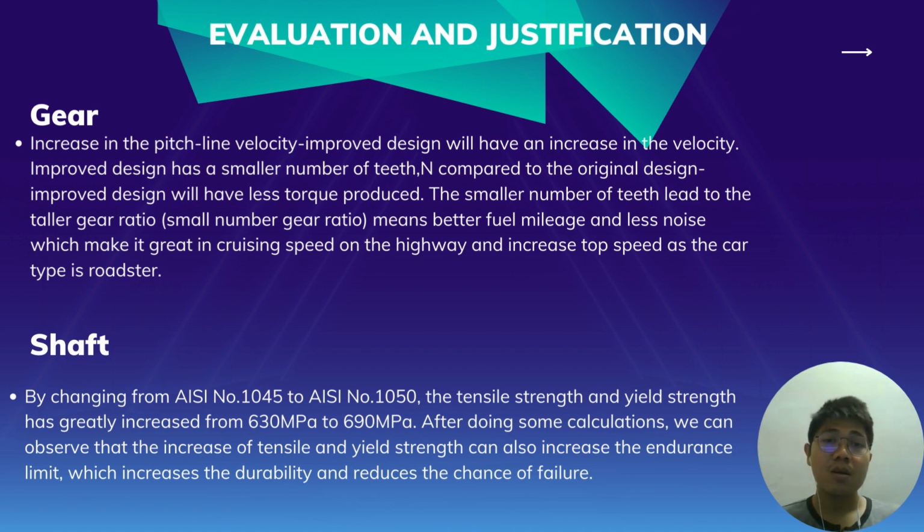And then in the shaft, by changing from the old to the new design, there will be a great increase in tensile strength and yield strength from 630 megapascal to 690 megapascal. After doing some calculation, we can observe that the increase of tensile and yield strength can also increase the endurance limit, which increases the durability and reduces the chance of failure.